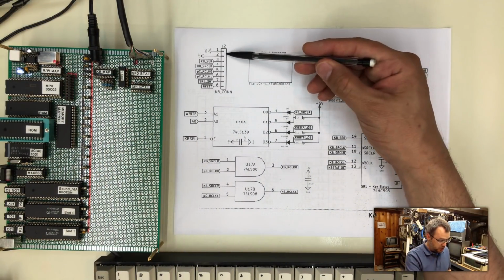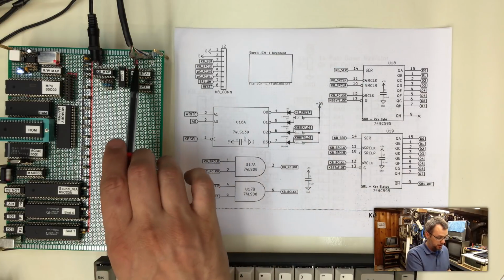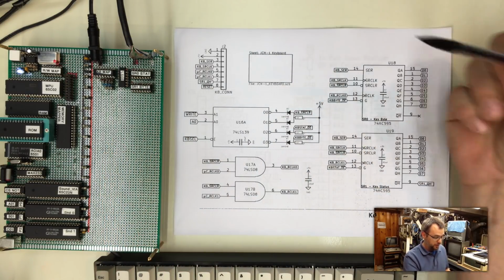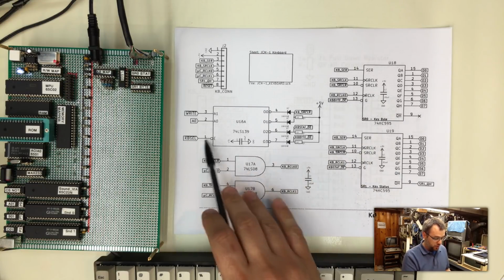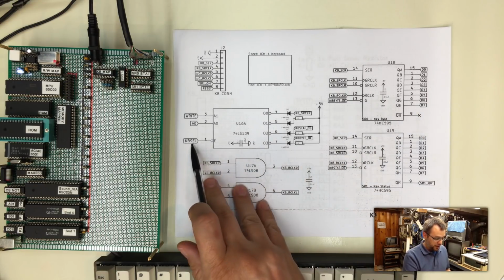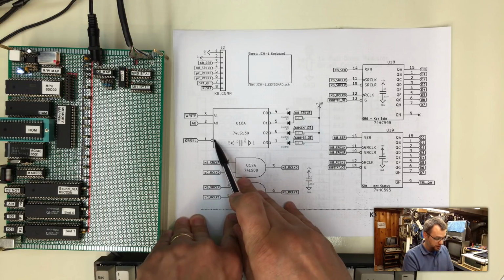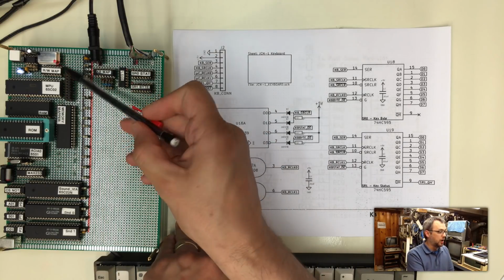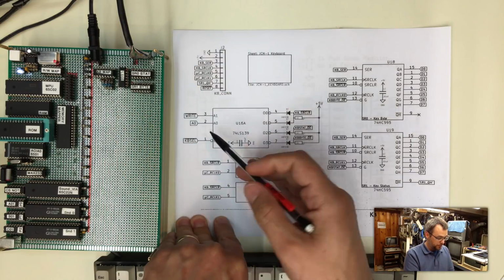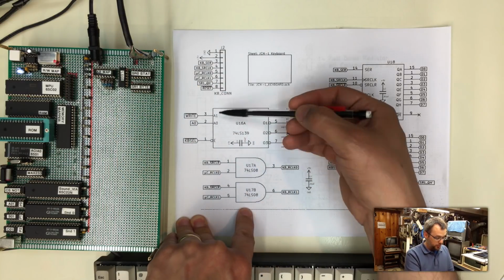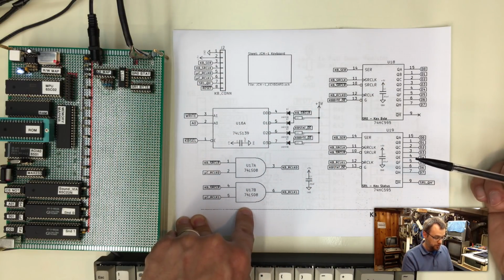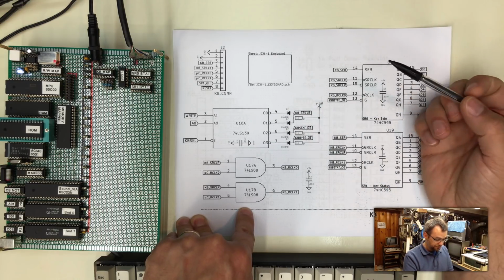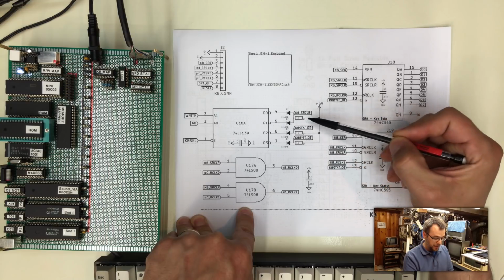So we have a new keyboard connector, as I talked about last time. It's an 8-pin connector, so I have that represented now. Here's our 139. We have our KB cell as our select line for the entire chip, and we have our write coming out of our RW map chip, and our A0, so we can tell the combination of those two logics. And then those come out as our values of 0, 1, 2, or 3, which then again come out